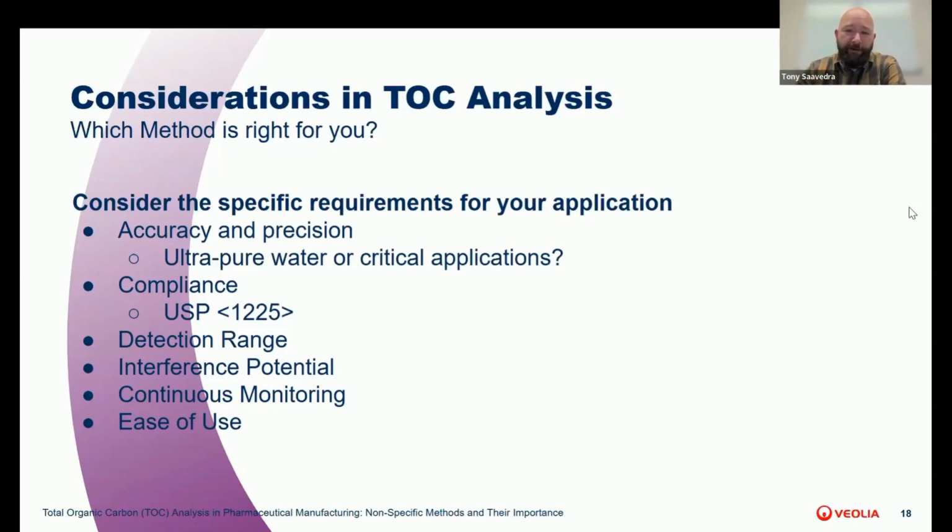Next, think about regulatory compliance, and this is a big one in the industry. Both membrane conductometric and NDIR methods can be validated according to USP 1225. But here's a key point. Direct conductometric cannot be validated to the standard, which limits its use in regulated pharmaceutical environments.